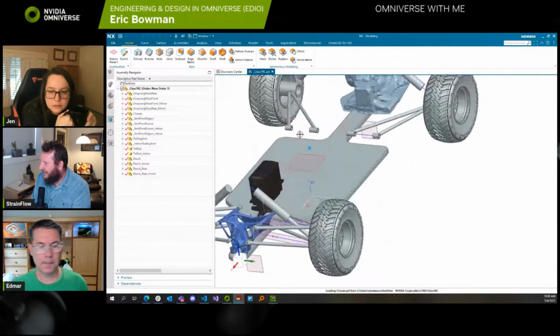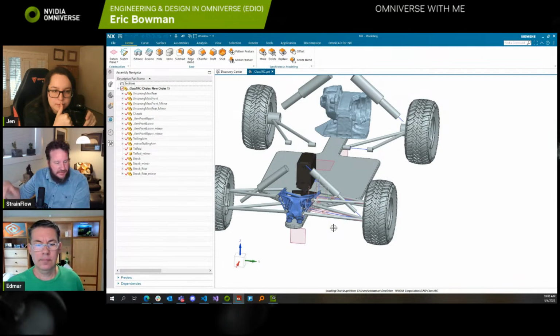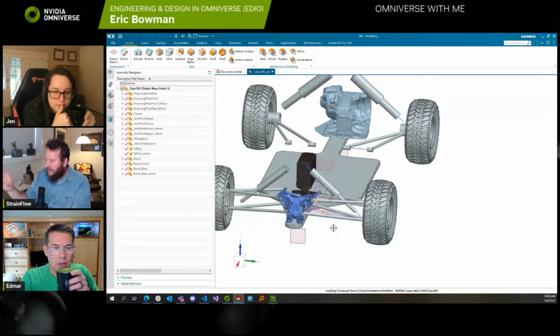I'm actually designing the car from, you decide, well, what camber do I want the wheels to have? What roll center? What are the dynamic properties that I want? And so then you go and draw sketches to achieve those. And then you have, as a skeleton, and then you build your parts on top of that skeleton. It's really fun.